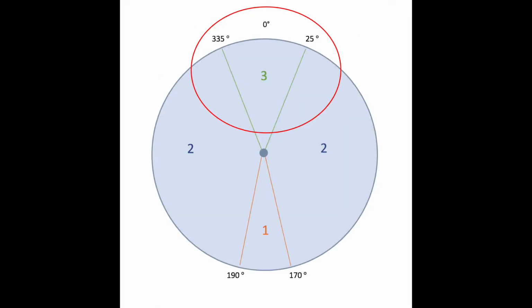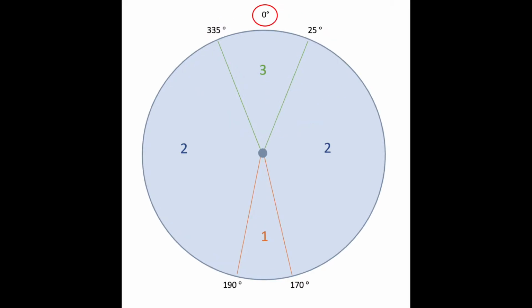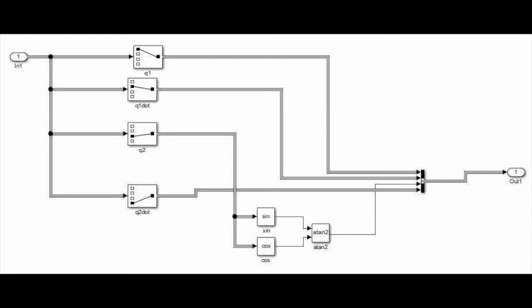After finishing the swing up, we began working on state 3, the balance state. In state 3, we had a discontinuity at 0 degrees. In order to use this state, we had to linearize the system around the point at 0 degrees. We first needed to alter Q2 again using the same atan2 technique used in the previous subsystem.